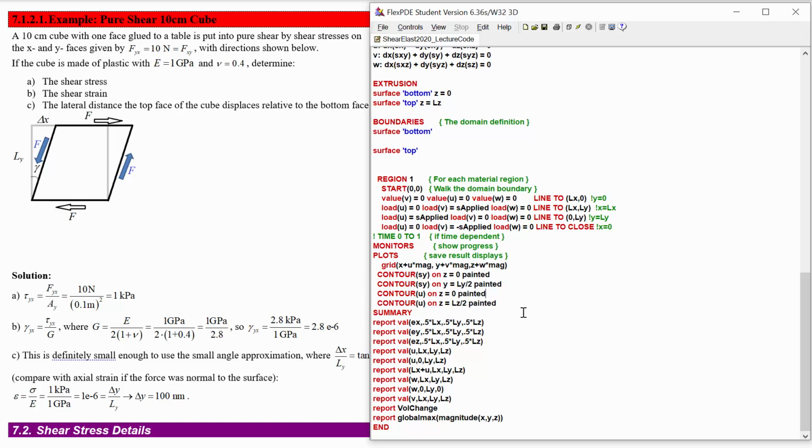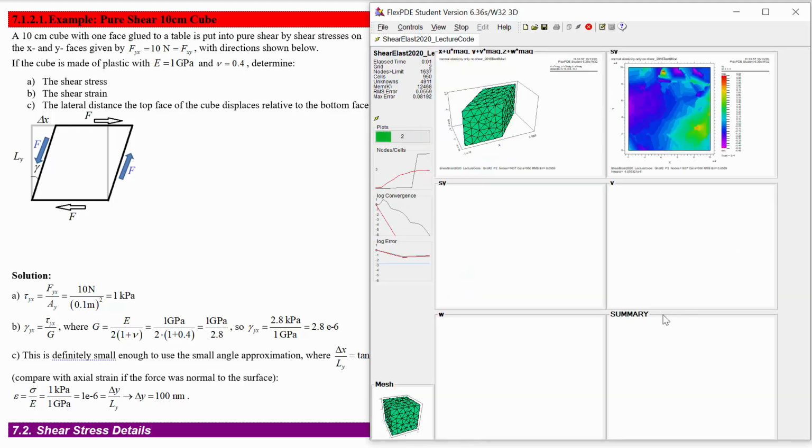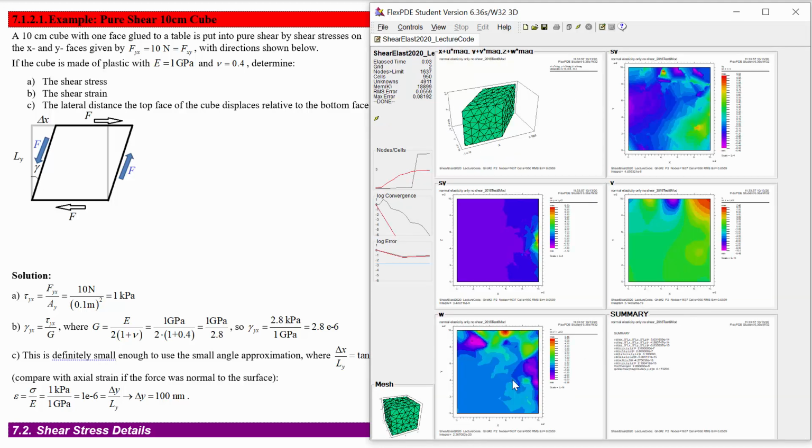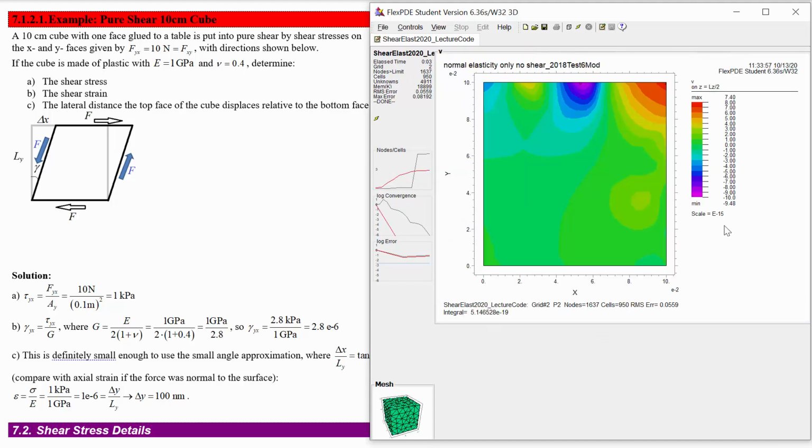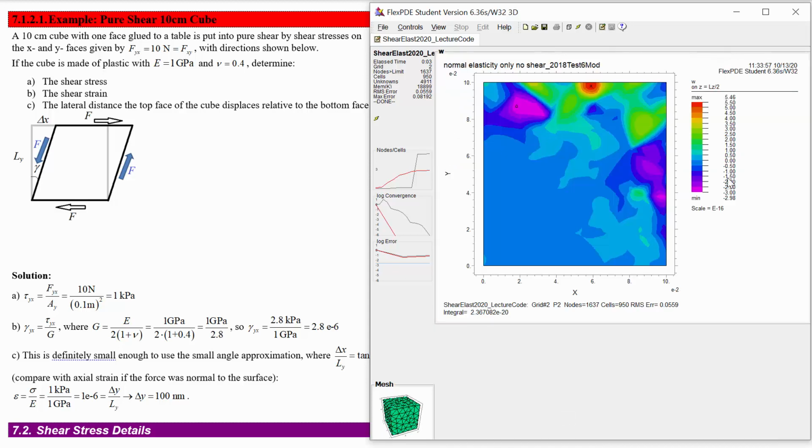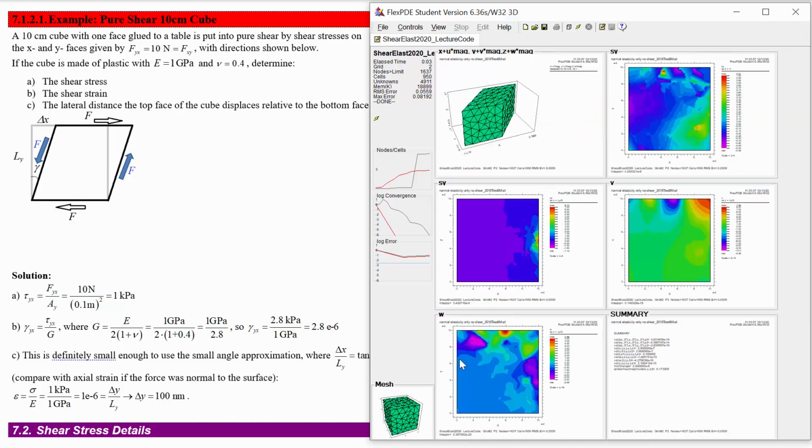So what if instead of the x displacement, we have a look at the y displacement and z displacement? Now we expect these to be just 0. What do those look like? Looks kind of funky, but it's at E minus 15, so that's just 0. We're just seeing numeric precision there. And this one, E minus 16. Yeah, so no displacement in the y or z directions.